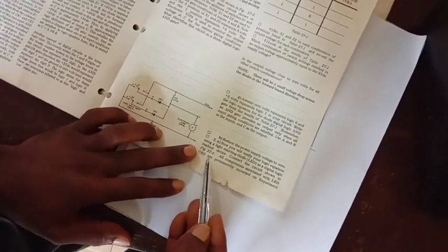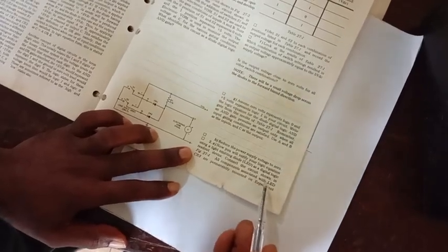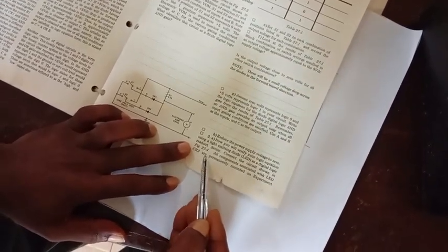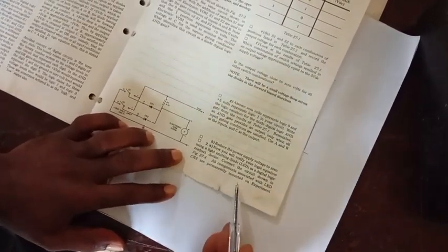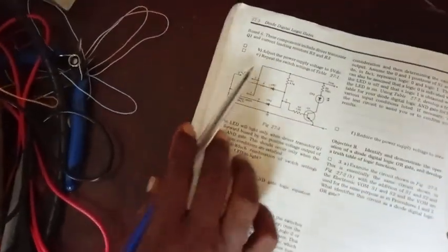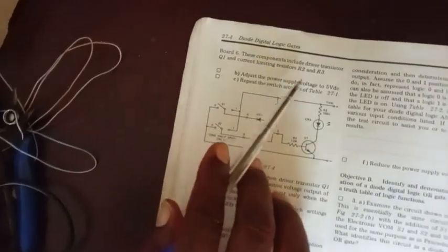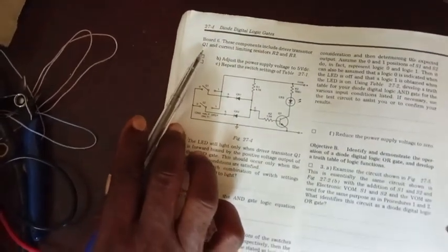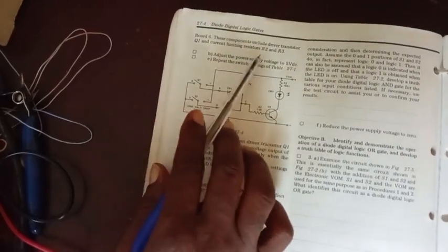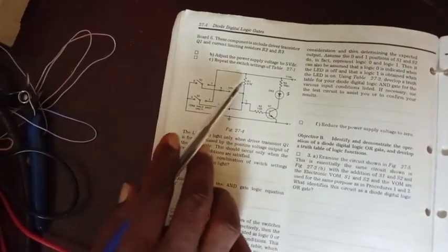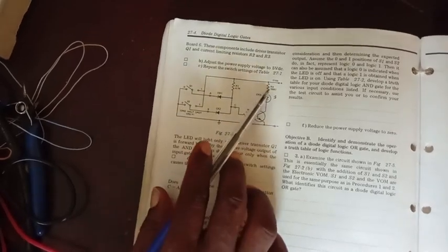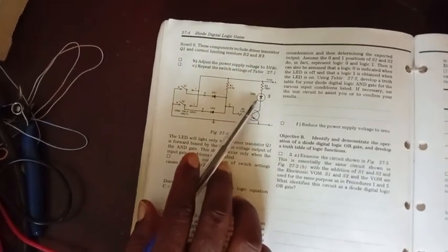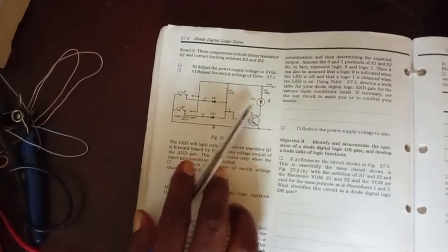So connect the circuit shown in Fig 24 to 7. All components associated with LED CR3 are permanently mounted on. Okay, but we are not using this. We are using a breadboard. These components include the driver transistor. Yes, we use a transistor, and then we use resistors, resistor 1 and resistor 2. This is the circuit. We need a 4.7 K resistor. We need a 150 ohm resistor. Then we need a miniature lamp or LED, anything that can give us light here.